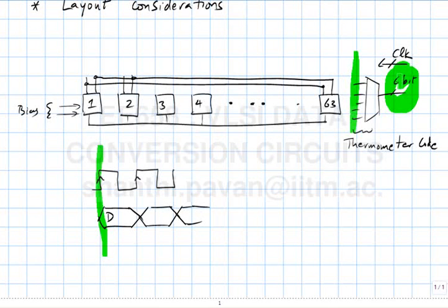Not only that, the moment you propagate those lines all the way across the array, you have an additional problem, which is, do you think the decoder outputs will take a long time to reach 1 or to reach 63? They will take a long time to reach 1, they will take a short time to reach 63.